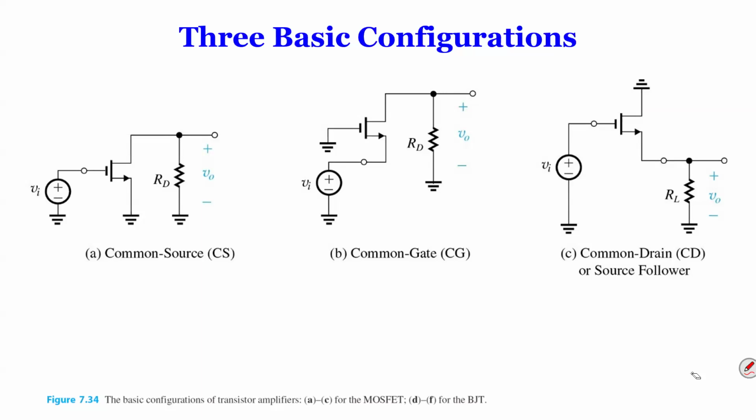Now, this circuit per se doesn't include the DC. If you look at it, we didn't include DC. So this is basically more like a small signal equivalent circuit. We didn't use the actual small signal circuit, but we still use the symbol of a MOSFET, and we removed all the DC biasing, like the power supply, the DC bias, the gate biasing, and so on.